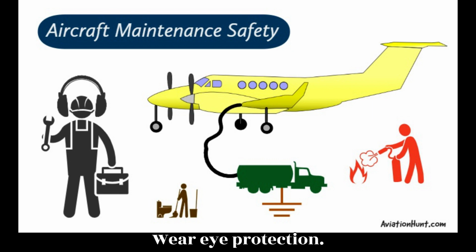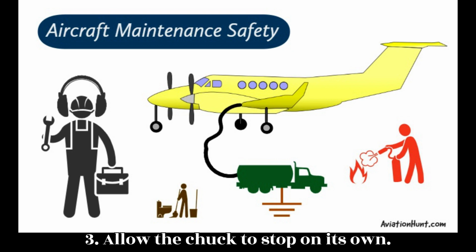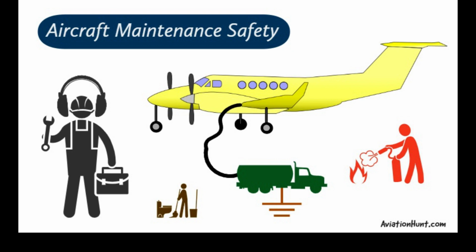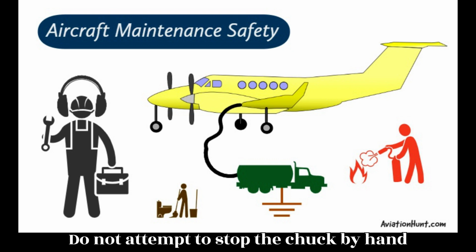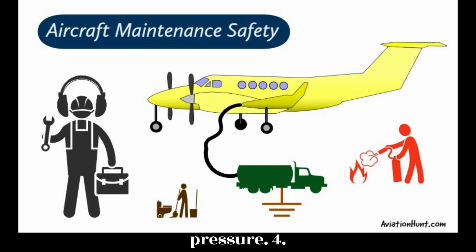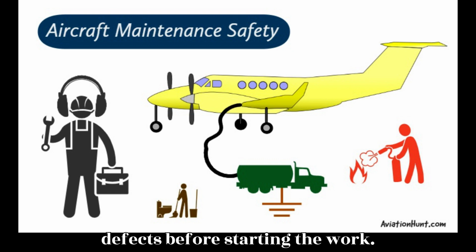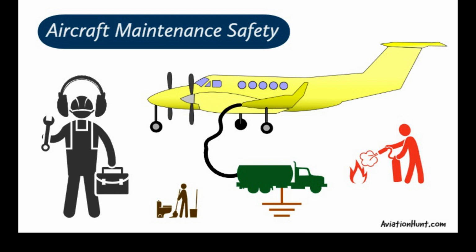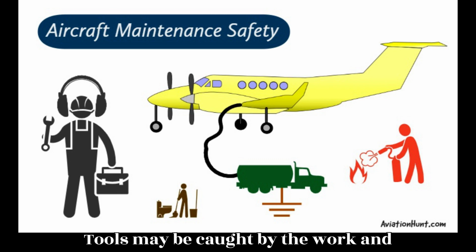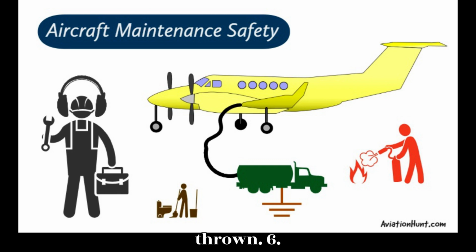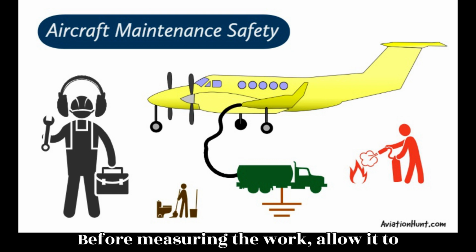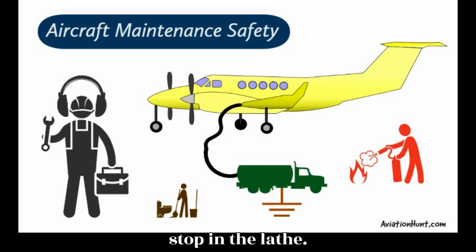1. Wear eye protection. 2. Use sharp cutting tools. 3. Allow the chuck to stop on its own. Do not attempt to stop the chuck by hand pressure. 4. Examine tools and work for cracks or defects before starting the work. 5. Do not set tools on the lathe. Tools may be caught by the work and thrown. 6. Before measuring the work, allow it to stop in the lathe.